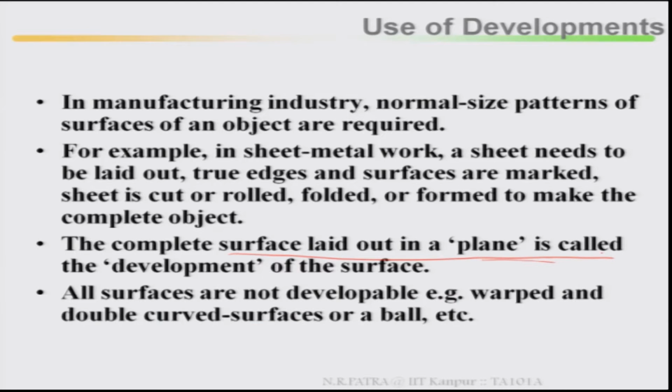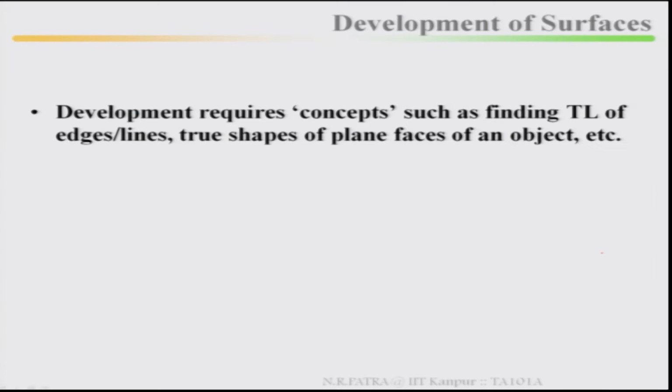All surfaces are not developable, that is warped or double curved surfaces or a ball, etc. Then development requires concepts such as finding true length of edges, lines, true shape of plane faces of an object. Now, here the concept of true length will come into picture, because we are taking the line as a true length.